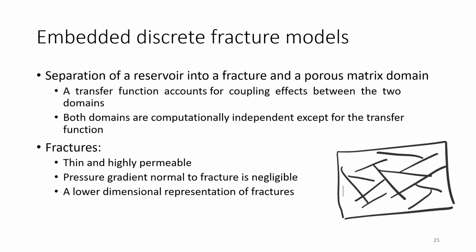The embedded discrete fracture model is something that's not that common, but I recently noticed that it gets incorporated in a few more of the commercial tools and also open source tools you can use for groundwater modeling. So it's kind of a combination. So you have this porous matrix flow and the fractures on top, but you do not have these kinds of domains continuously, but there is a constant interaction at the end of fractures with fractures and porous matrix flow. Okay,